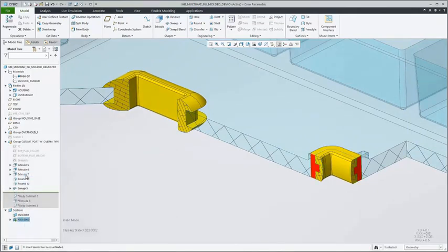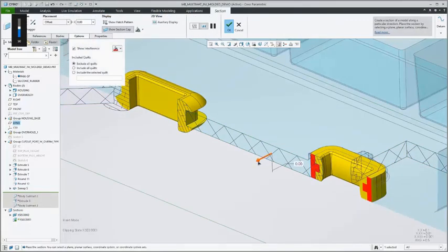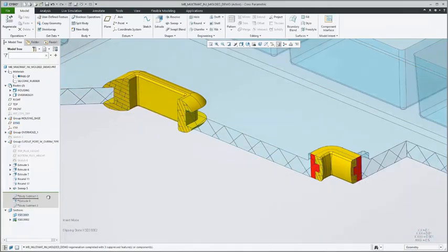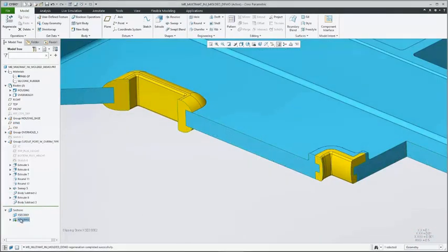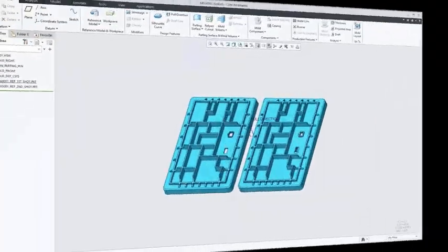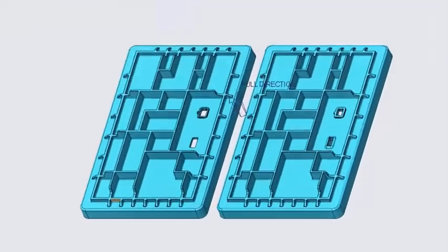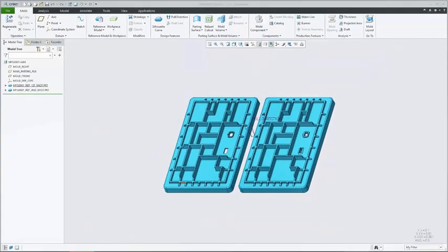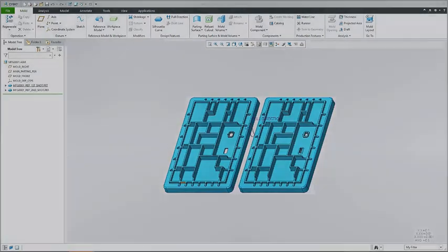In addition, you can perform body interference and clearance checks within a cross-section or across the entire part. And finally, you can use data sharing to prepare various flavors of reference parts for mold design. Overall, multibody can ease the design of injection molded multi-material parts significantly, avoid the complexity of dealing with assembly objects and external references, and instead use a single model with multiple bodies.